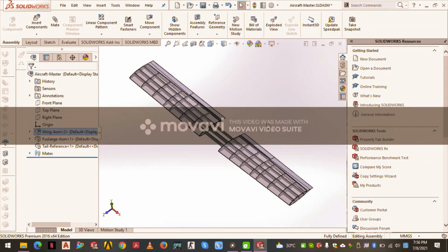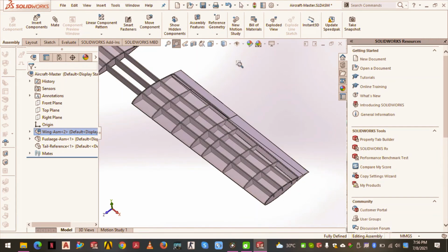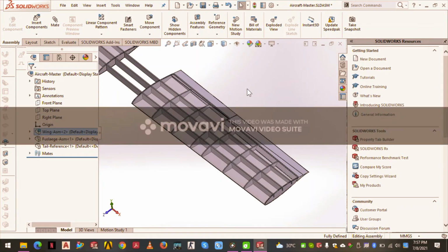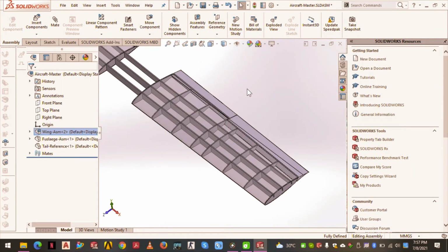And how we are going to do it, a little bit about that as well. We will use a composite sandwich structure, which means we will take about an inch thick pink foam, and we will sandwich it between glass fiber layers from all sides. It will give you a highly rigid and high strength composite sandwich structure.